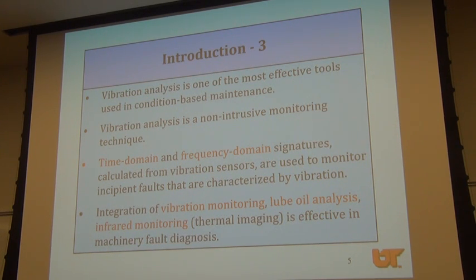Then it says here, why do we do vibration analysis? It's one of the more common tools for condition-based maintenance. That means you're looking at the condition of the machinery based on measuring certain things. That measurement must reflect the fault in the device. So if there is vibration, that's kind of reflecting some kind of fault, right? So it is used in condition-based maintenance or, some folks call it, predictive maintenance.